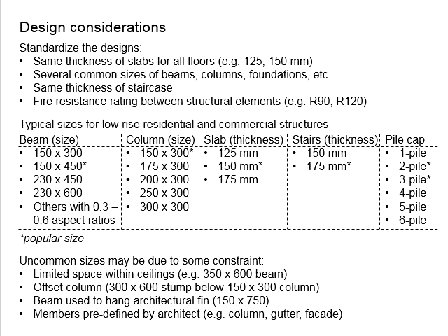Sometimes when the load is relatively high, you may require a taller beam, as long as the aspect ratio between the width and the height falls somewhere between 0.3 to 0.6. That would be a good ratio for a typical beam, where the beam performs quite okay under bending moment.